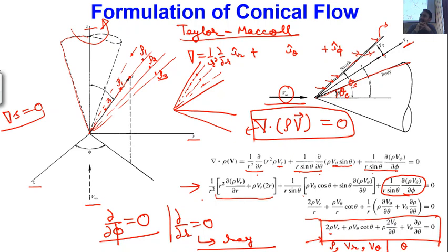This point is clear. Another important point is that this is nothing but an adiabatic situation. We are not doing any heat transfer over here. So if this is an adiabatic situation, then we know from the energy equation that in these two regions, one over here and another over here, the total enthalpy remains constant for adiabatic flow, because total enthalpy changes only when we are adding or removing energy.